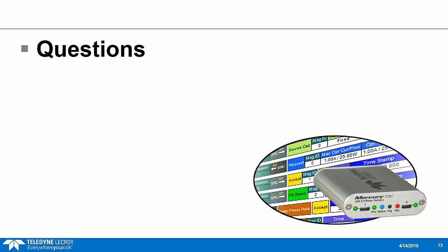Okay, another question. Why would a source want to renegotiate a power contract? Isn't that for the sink to renegotiate? Well, there's times that a source may want to renegotiate the contract. He can always do so by sending his source capabilities, say, if his ability to supply power has changed. So possibly another sink on another port has been disconnected, so now he has more power to source. Anytime he issues that source PDO, that means his sink partner is required to make a request, and that's something that is actually tested in compliance. Good. Looks like that is most of our questions that I can see so far.